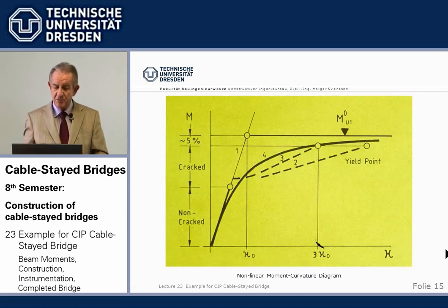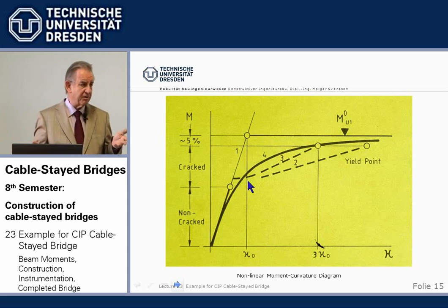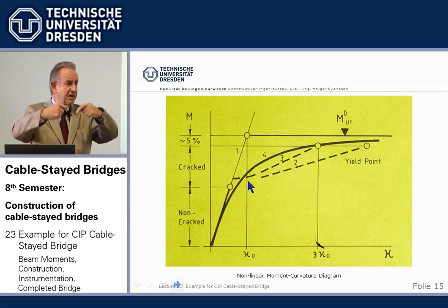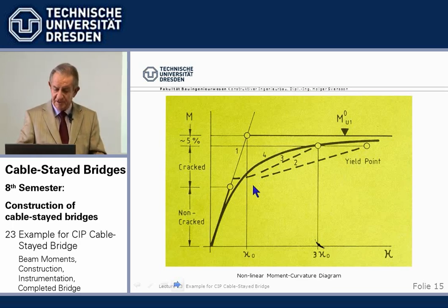With a moment curvature, kappa we usually use for curvature. This is the curvature, and these are the corresponding moments. This would be linear if we would have steel unyielded. But here, taking into account the actual reinforcement, the actual post-tensioning at every cross-section, we come to this, and all this is fed back into the computer and run again until we get it stable.